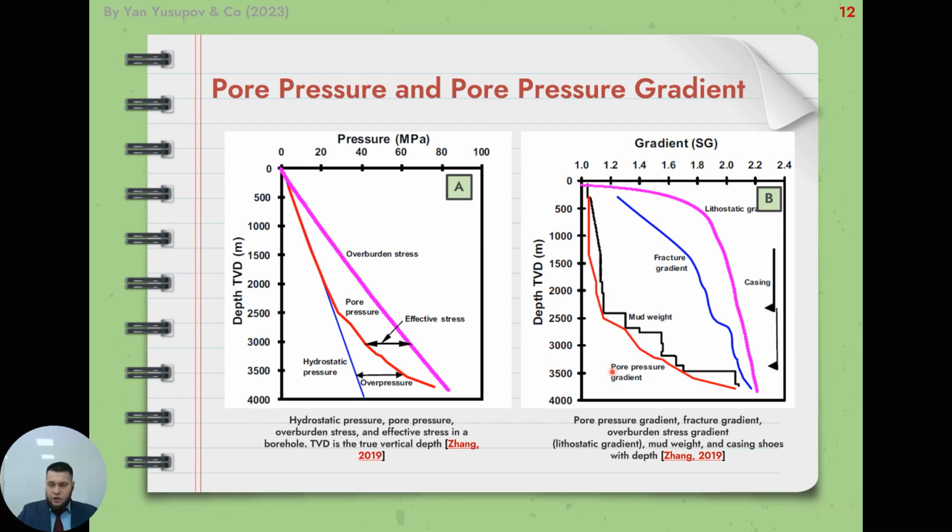We will discuss fracture gradient and wellbore stability in future lectures. The topic of today's lecture is only pore pressure, underpressure and overpressure. The drilling fluid, mud, is applied in the form of mud pressure to support the wellbore walls to prevent wellbore collapse during drilling. To avoid fluid influx and wellbore instability in open hole, a mud weight heavier than pore pressure is needed.